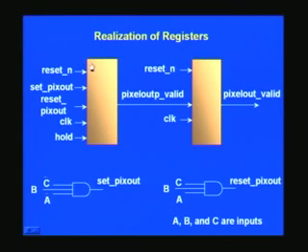Here what you see in the picture is two registers as such. One register output is called pixel out P. P stands for previous, and it is a valid signal. In microprocessors you would have encountered data and its corresponding data valid, and this is precisely what it is, a valid signal, not the data itself. Here this is one of the designs I made for video scaling. We will not go into the details of the same, and this is just an extract of a portion of that.